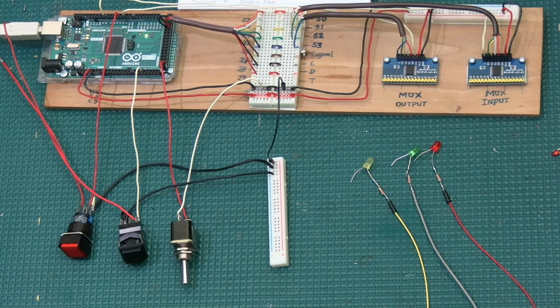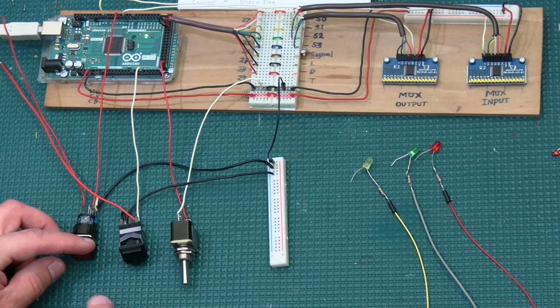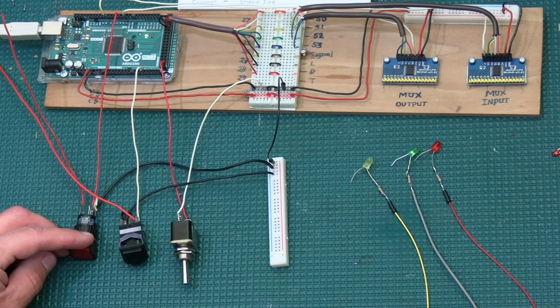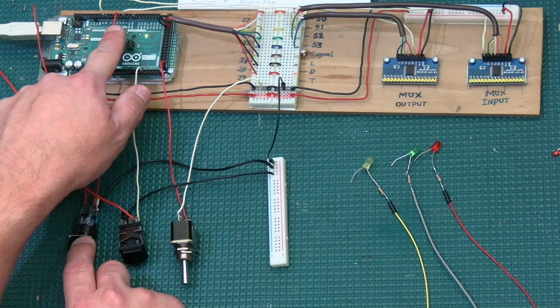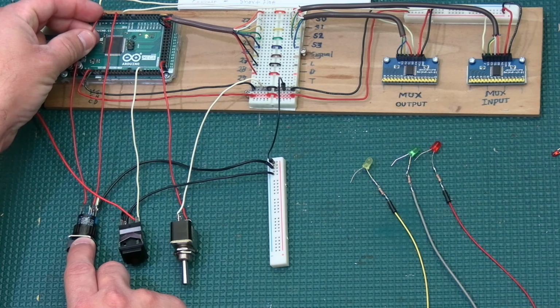Alright, so like I said, these buttons right here are basically just a button and an LED, but they're together, so there's nothing in there that should make you scared just because they have a lot of leads and everything. Just treat them as a button and an LED. So we're going to go ahead and disconnect this one first, the red one. That's going to go to number 6 for that LED. So the button is on number 4 over here, and then the LED is going to be on number 6, which is going to be right next to it there.